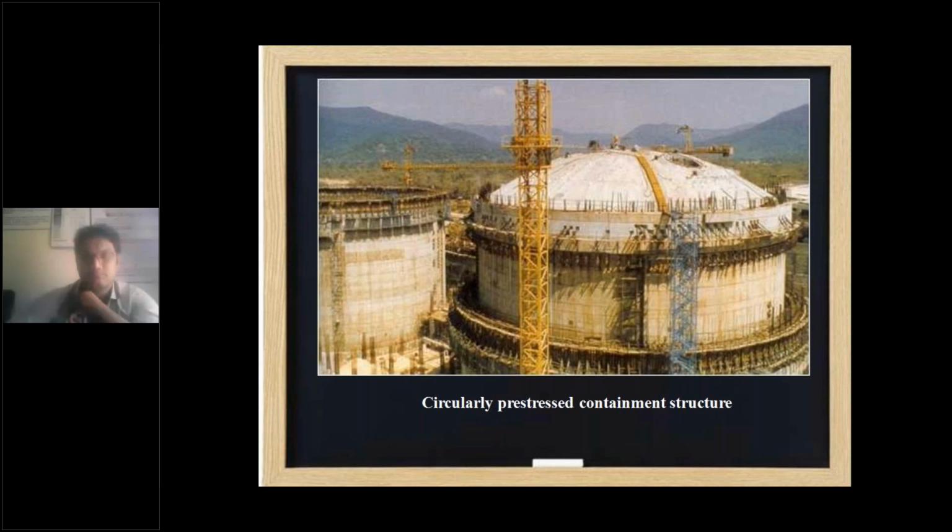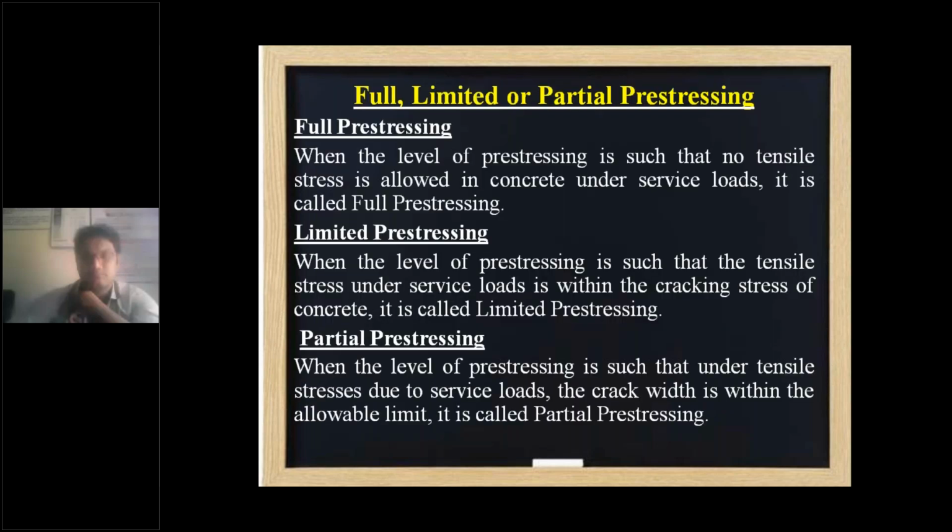Here you have to observe what type of stressing is adoptable for that particular structural element, based on its shape and its mode of behavior, its mode of doing the stressing. There you have to decide whether you want to go for hydraulic stressing, mechanical stressing, or thermo-electrical stressing, or else linear stressing or circular stressing. You have to decide that before you do either pre-tensioning or post-tensioning, right? So this is about the types of stressing systems.